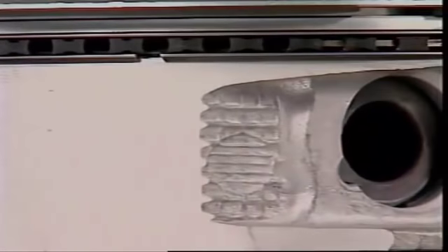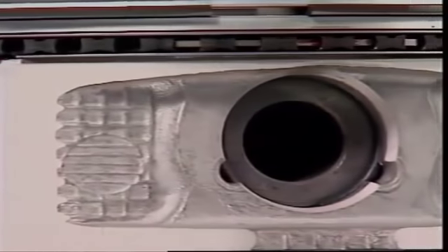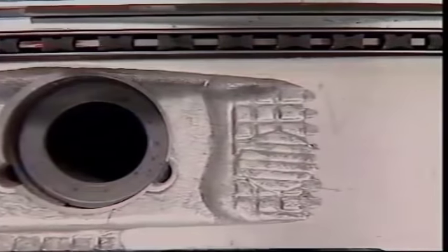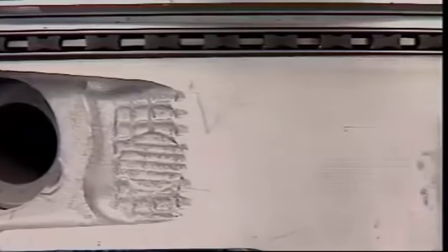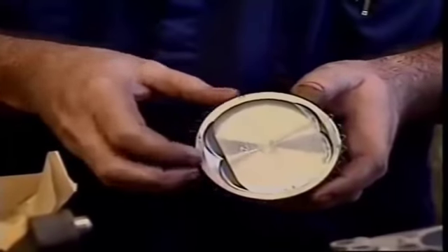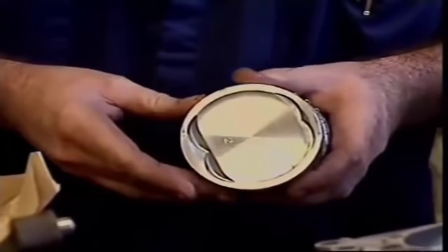Many oil rings are segmental types with 3 or 4 segments. They have 2 side rails and an expander, which also acts as a spacer for the rails. They depend on the expander to hold them against the walls. The expander is made of thin steel with a series of crimps to give it an outward spring force.